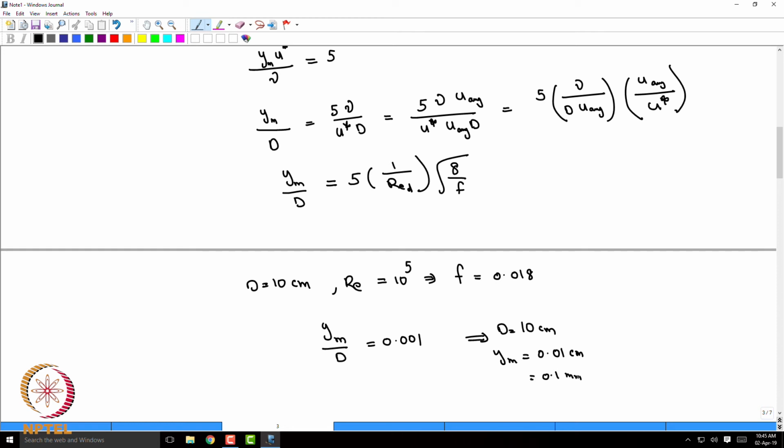So that means, if there is a flow that's happening on a very rough surface, that flow is going to get affected by the roughness. That flow is not going to be smooth. Actually, another way of saying it is that the wall layer itself gets disrupted because of the roughness. The roughness that you might not have imagined would play a role actually will destroy your wall layer and will affect the entire flow field. Okay, therefore, pipe roughness affects turbulent flow. That's the takeaway point. Is that clear?